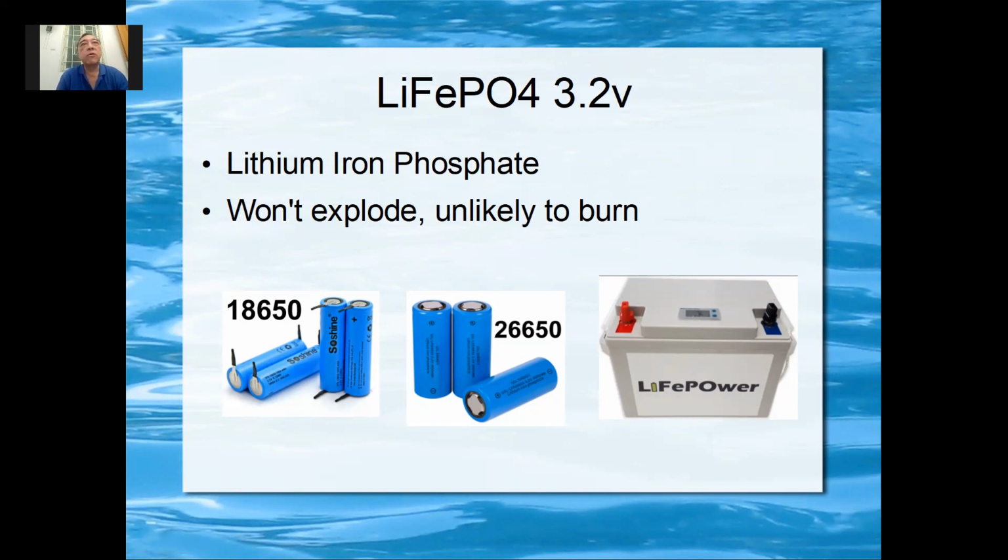So once it cuts off, the other batteries in series will not get charged. It's the same like you got 4 people on the table. The person who finishes eating, full already, he will stop all the food from coming in, clear all the food, no more food. So the one who eats slow will not have food. So that battery will not be charged.